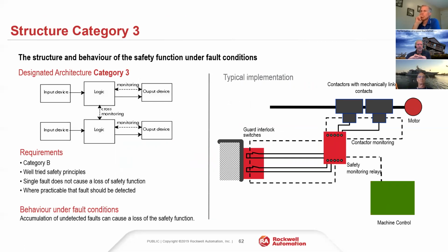There's the 3 Ds of safety, which we didn't actually put a slide in on, but I'll mention it here verbally. So for safety principles, good safety principles and design, whether it's in a product or in the safety circuit, whether it's in the entire system, the entire application, there are 3 Ds to concern ourselves about. And those are duality, diversity, and diagnostics.